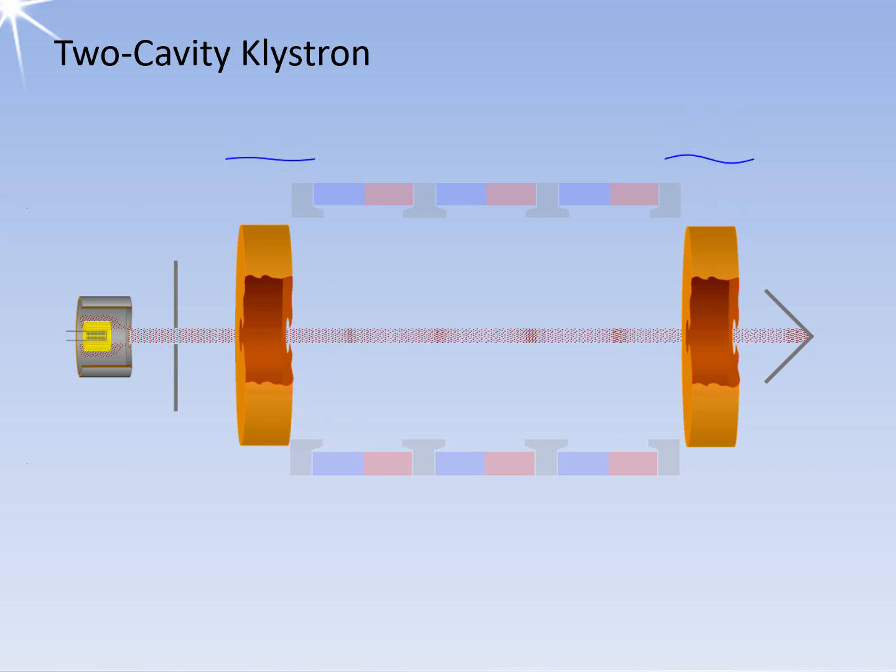When the electron bunch passes the first wall of the cavity, the free electrons in the wall material are displaced and migrate to the opposite side of the cavity. But the electron bunch quickly arrives on the other side as well and sends the electrons back again. This creates the output oscillation in the resonator. Provided that both resonators are constructed the same and the mean velocity of the electrons is constant, then the frequency of the output oscillation is the same as at the input of the tube.